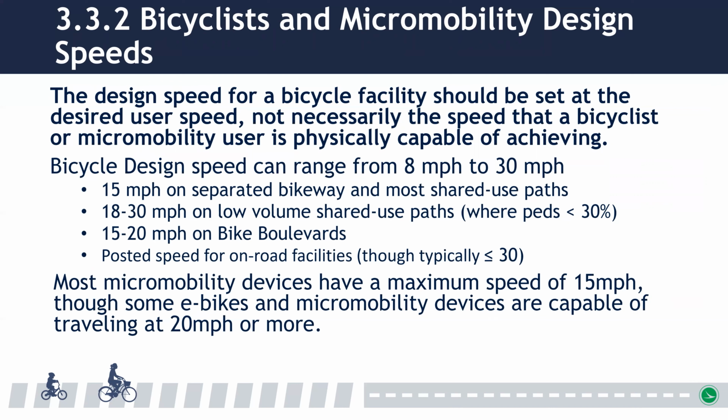There is no one-size-fits-all design speed for bicyclists and micromobility users. The MDG provides information on the things designers need to consider, provides recommended speeds and ranges, provides information on dealing with areas where speed changes occur, and provides acceleration and deceleration information.